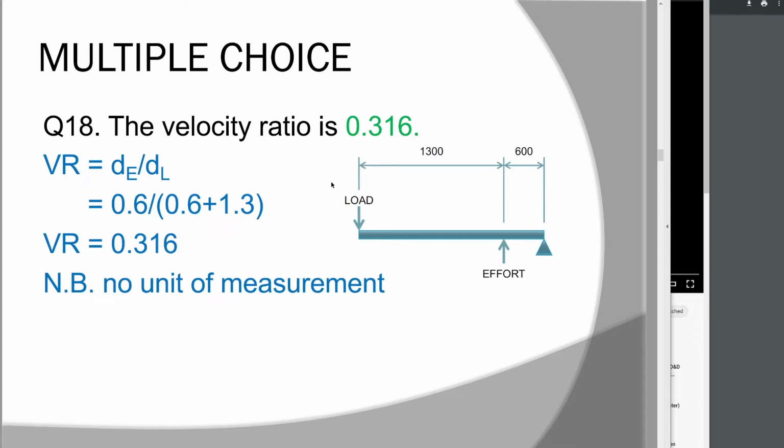Okay. Velocity ratio, we just spent some time talking about velocity ratio. We said that velocity ratios are calculated based on dimensions. And the trick for this question is that we always measure to the fulcrum. So it's 600, I've used meters because I said we should always try and use base units except for millimeters squared and megapascals. So this effort is 600 away from the fulcrum.